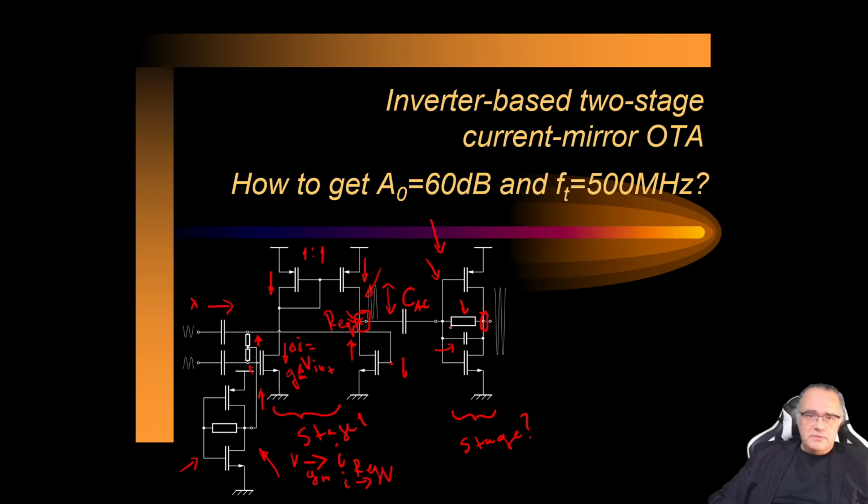If we use this amplifier in a feedback configuration with negative feedback, there is a risk that the negative feedback becomes positive because of the phase rotation in our amplifier. This is why we use Miller compensation. This is the amplifier, so let's see how we analyze it further in more detail.